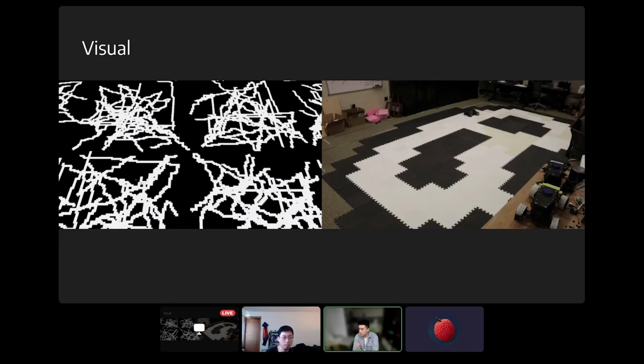So at least for Isaac Lab tasks, our training environments are relatively simple. I might have misspoke: we didn't stack 3080s, we each just individually trained on our own 3080s. And in fact, at least in my case, I was only occupying about half of the GPU memory that was available. I think it only took about 5 gigs of VRAM. So these tasks are really not that compute heavy, and I think the cloud infrastructure should be totally fine.